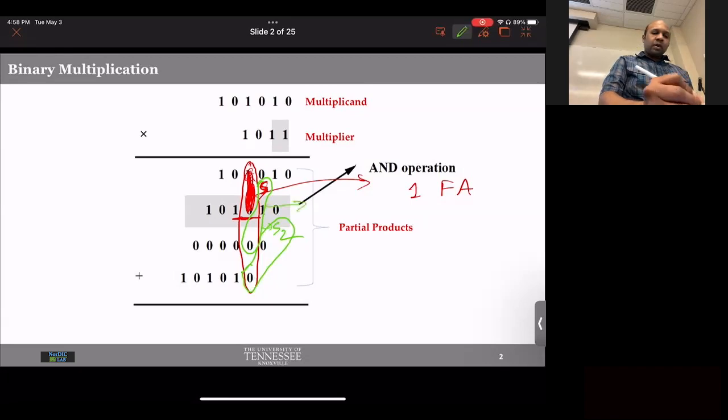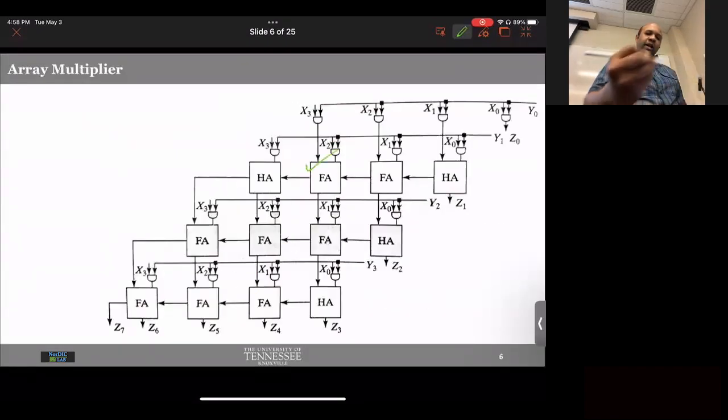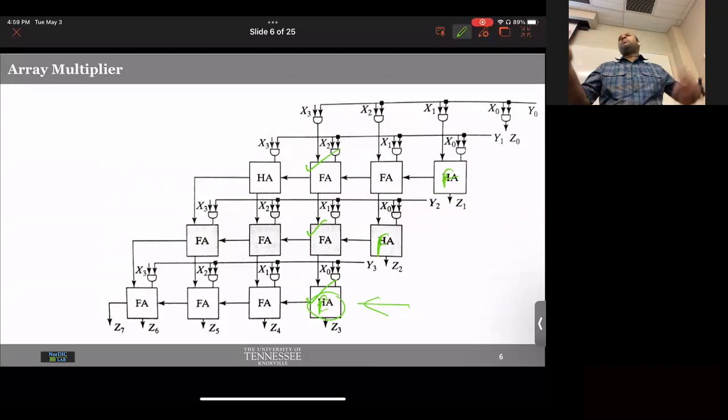So you have another adder and you have another adder. How many adders will you need to add 4 bits? 3 adders, right? And let's see. You have 1 adder, 2 adder, 3 adder. The last one is a half adder because there is nothing before it. I mean, nothing will happen even if you use full adders everywhere. You're just being wasteful. You're wasting a lot of transistors. Any problem? Anyways, you'll connect those transistors and set them to ground because no carry in, 0.